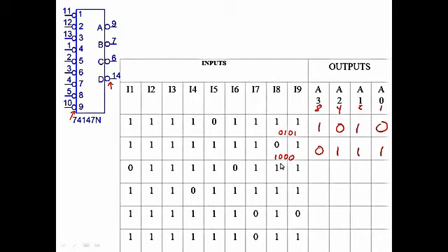And one of the reasons we do that is zeros carry more current with them. So there may be a reason where you need to put more current on there to drive chips. This one, you notice we have 2 of them that are low. This particular chip, the 147 chip, actually is a priority encoder. So even if you have multiple inputs tied low, it'll always pick the highest one.